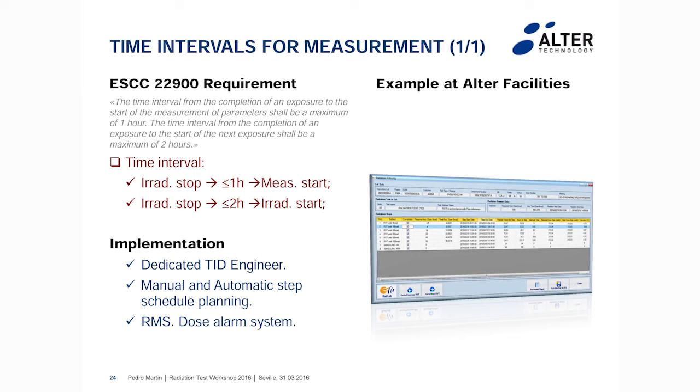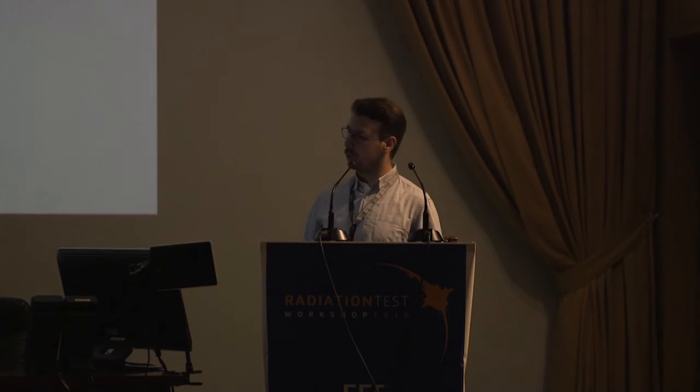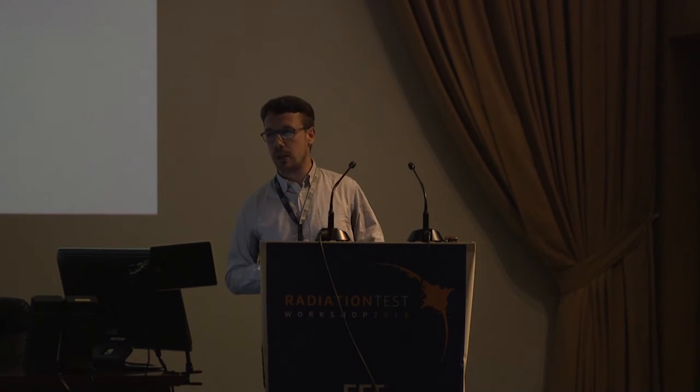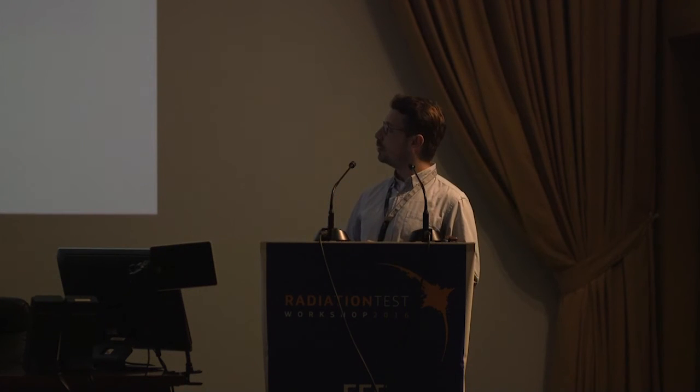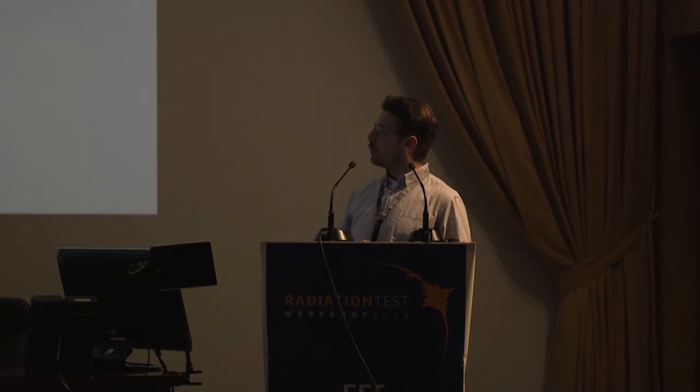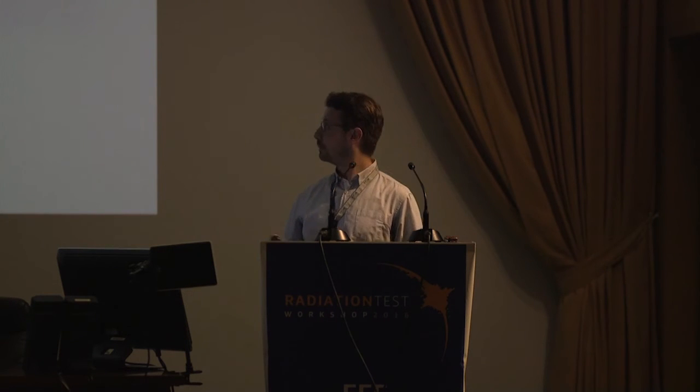We recommend to always have the same dedicated TID engineer for each lot, because you can control what time you need to perform the electrical measurements, because the second requirement is that you only have 2 hours to resume the radiation.